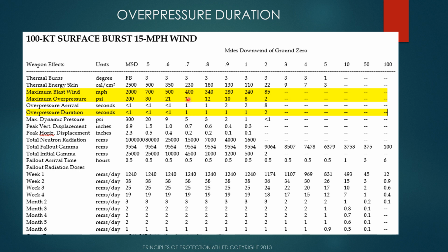So if you're designing a rated shelter, you've got to withstand this overpressure, and on the air manifolds and the hatch, you have to withstand 400 miles per hour. And keep in mind that in that 400 miles per hour, you're going to have flying debris. There's going to be a 10, 15, 20, maybe a 50-pound something flying in the air that can hit that air manifold. So it has to be able to resist that flying debris.